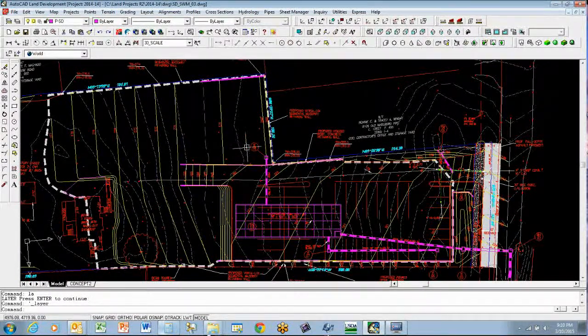Now it's important to note that an alignment simply represents a sample line, a line along which a profile will be drawn. So you want to make sure you capture enough surface to account for your alignment. You want profiles that show exactly what your storm drain, or whatever you've designed, really is doing in the plan. And it does no good if your alignment is too short.